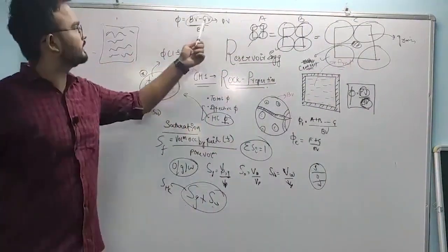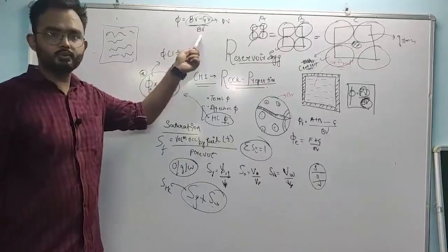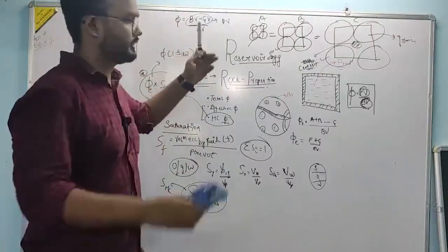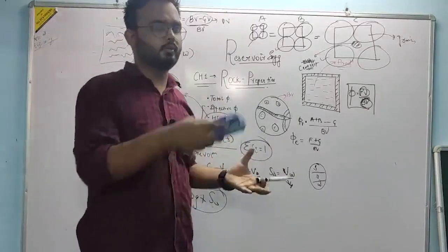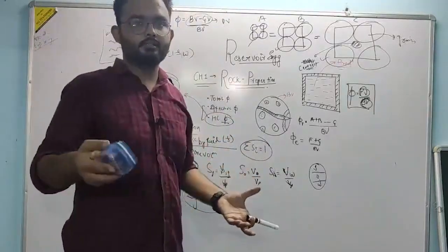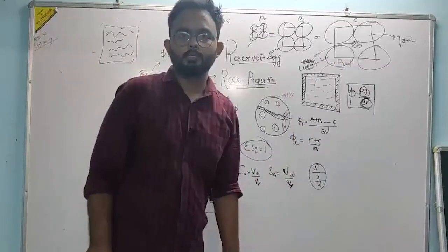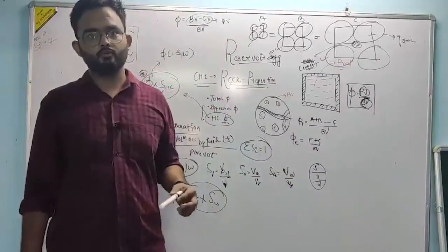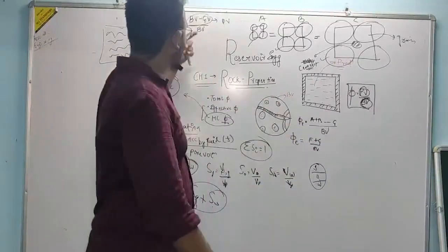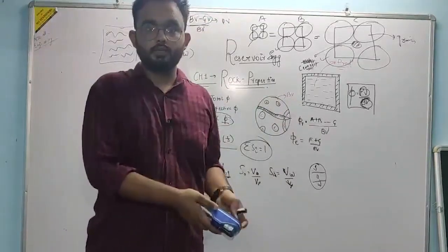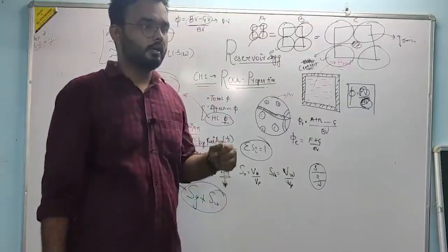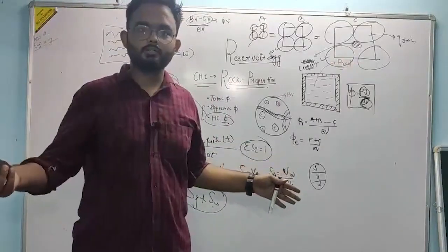You need to measure either of these. You can measure bulk volume using vernier calipers, and you can measure the scales. And if it's a cube, you can measure LBH, and if it's a sphere, you can measure 4/3 pi r cube and things like these, and that gives you the bulk volume. Now you can measure the grain volume by crushing the rock. That will give you the total porosity, because what's not crushed is the void, right?